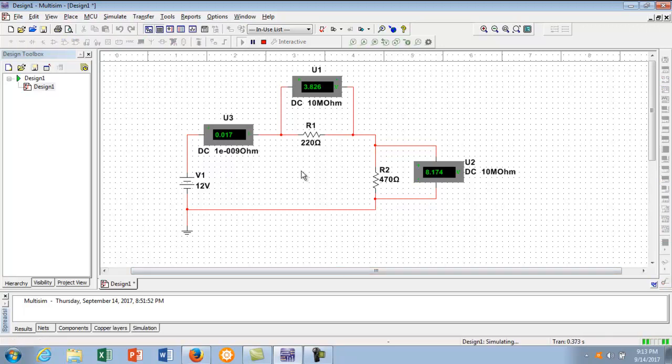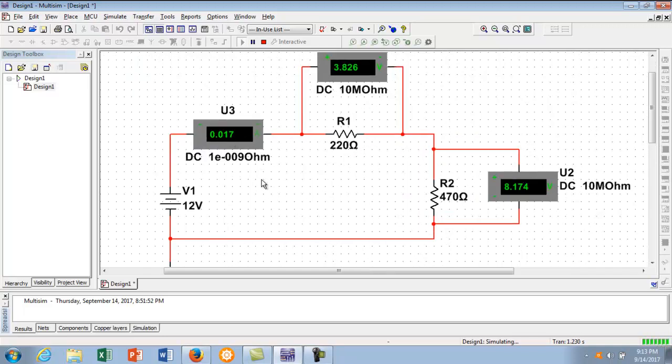We know this works if we go ahead back now to run. And now we have some values. Our 12 volt battery is putting out 0.017 amps through our series circuit. Our two resistors, well, I could have asked you to solve for R sub t to calculate this value. Instead, our two resistors still cause that to happen, but now you can read that this has 3.872 volts across it.